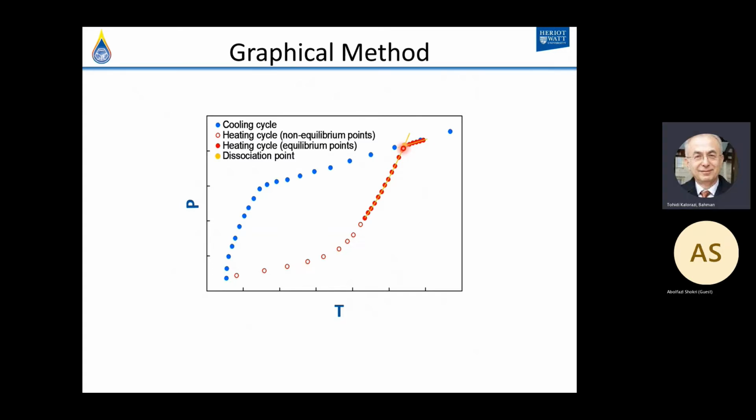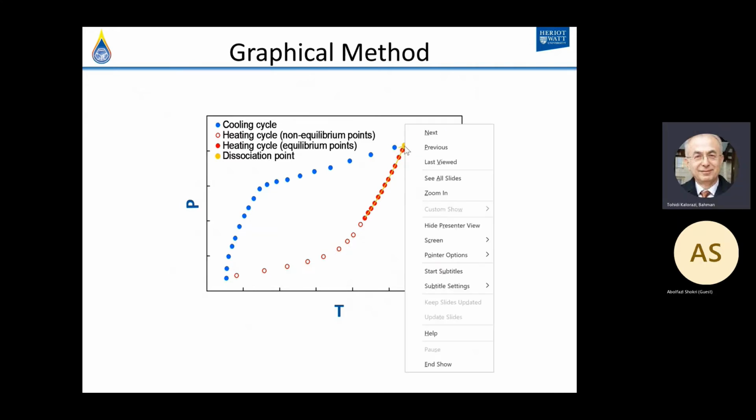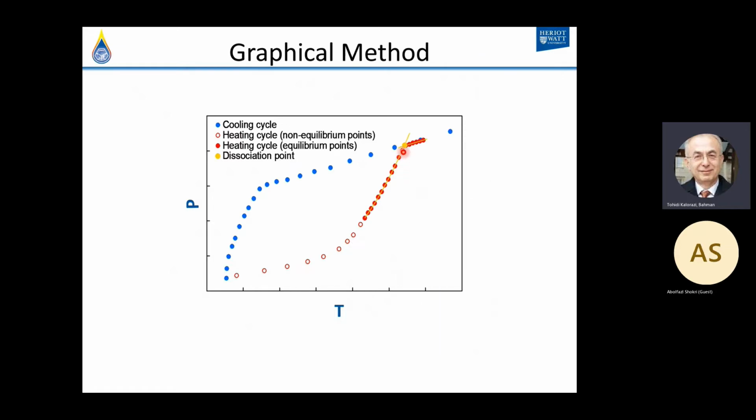And it means that at any point inside the hydrate curve here, there is a chance of hydrate formation. And because hydrate normally forms from small molecules, when it starts forming, we can have a significant amount of hydrate, as you saw in the video. So this is the point for design.